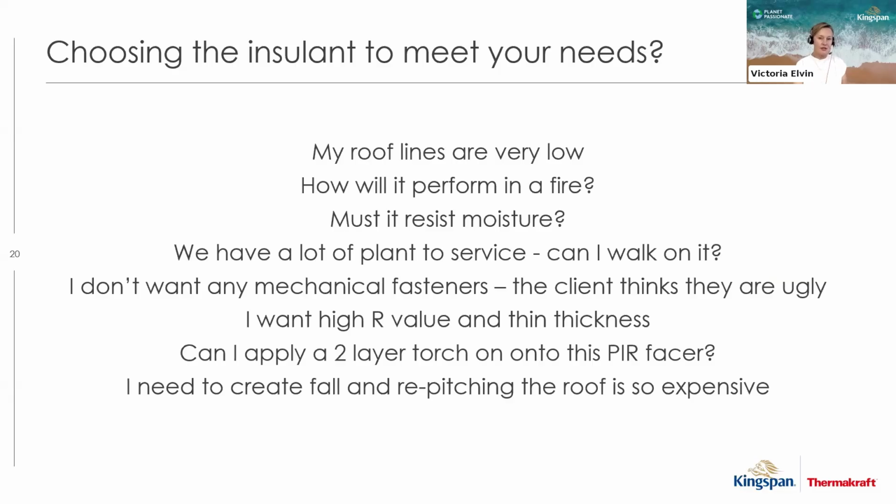They are thermoset closed cell insulation and are the leading product in warm roof design. They can be adhered or mechanically fixed to the substrate, and different faces on the PIR board can mean that different membranes or weather tightening systems can be incorporated in. For thicker roof structures where height is not as important, a fibrous insulation can be used, and some of those products are also non-combustible. These systems often have mechanical fastening systems, so they're not adhered. And of course, bio-based materials such as wood fiber can also be incorporated into a warm roof design, giving us great upfront carbon storage in the system.